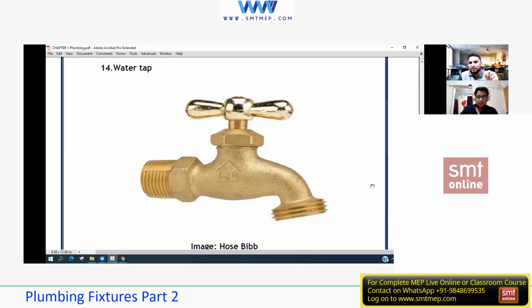So basically, a gate valve is installed in the tap. For example, if I rotate this one time, the gate inside will slightly lift up and a slight amount of water passes by. Second, somewhat more. Third, somewhat more. Fourth is the maximum. I'll get the maximum amount of water which can be drawn from the tap.